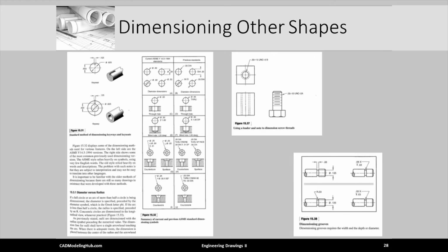These are some examples from the Bertolini textbook that show correct techniques for dimensioning compound holes, threads, and grooves. Notice the internal threaded hole. See how the leader is not pointed at the large dash circle, but it touches the object or solid thick circle. We will discuss more about threads and standard fasteners in another lecture.